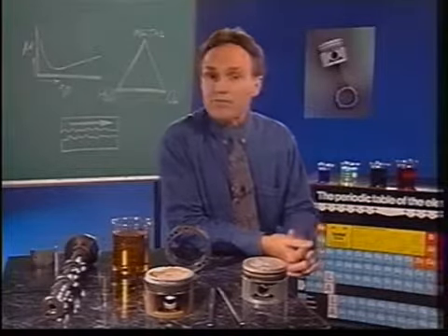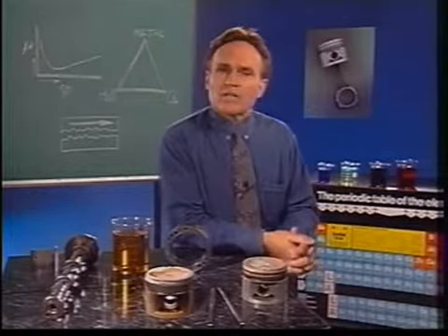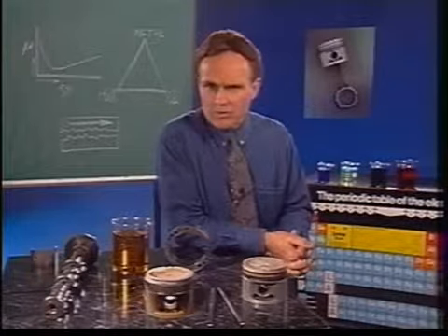Oil thickened by oxidation can cause bearing failure if the oil pump cannot maintain a sufficient flow, and it can even prevent an engine from starting. Oxidized oil also contains acids which can corrode metal surfaces.